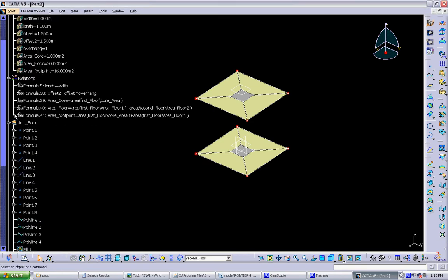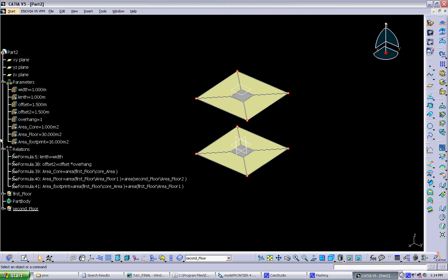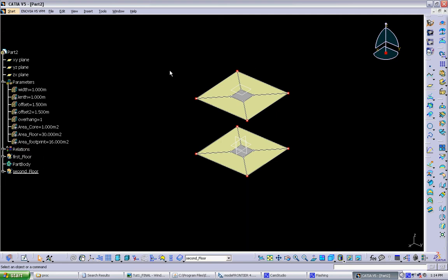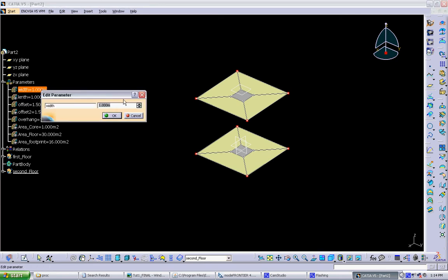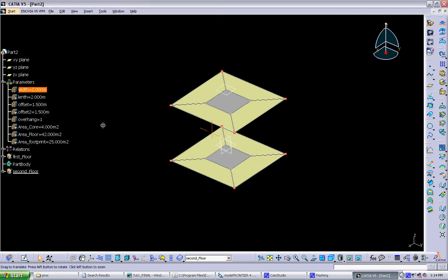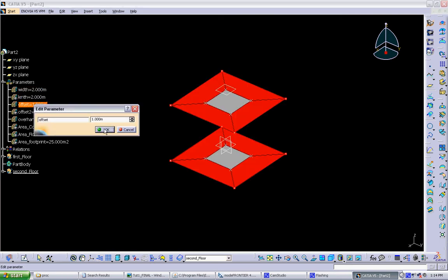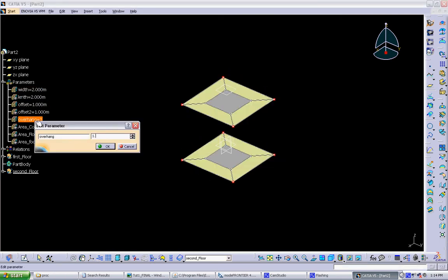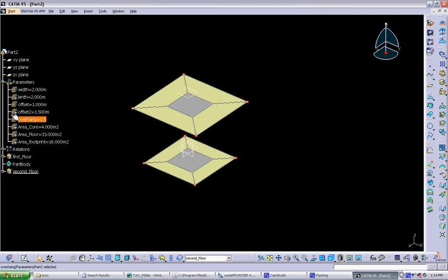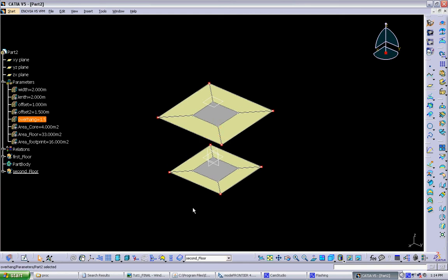so now what we have is our final first model. It's defined 2 floors, and you have control with 3 parameters over the size of the core, the size of the offset of the first floor, and the size of the overhang of the second floor. And it's giving you information back about both the area of the core, total floor area, and the area of the footprint. Now we're going to take this model into modeFrontier and do our first experiment just using these 3 input parameters and 3 output parameters.